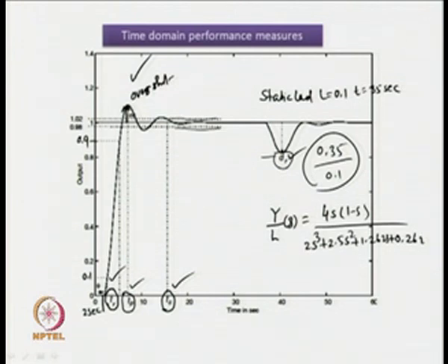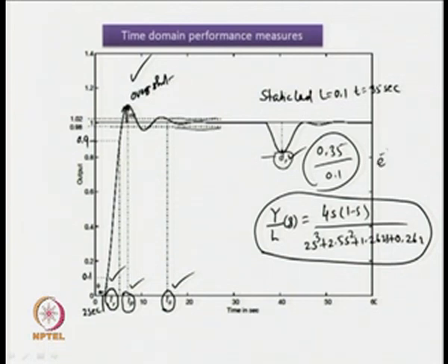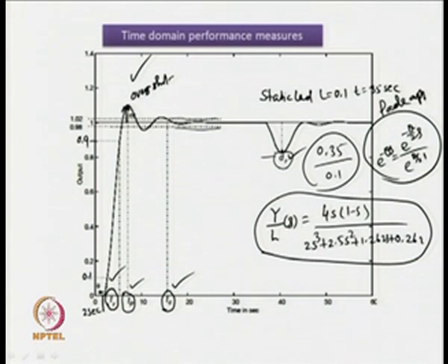So, the closed loop transfer function of the system with respect to the static load disturbance input can be given in this form, using the approximation for the time delay e to the power minus theta s as e to the power minus theta by 2 s upon e to the power theta by 2 s. This sort of approximation is often known as the Pade approximation.